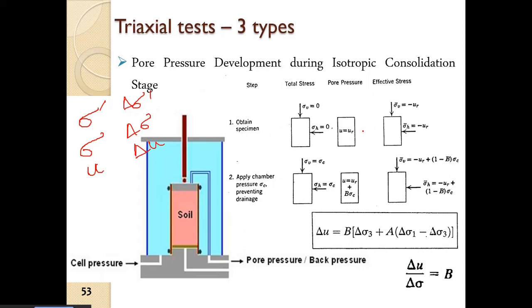If you remember, we had one sample inside the soil at a particular depth z. We had a pore water pressure of gamma w h. So this sample had an effective stress state of sigma dash equal to sigma minus u, where sigma is the unit weight of everything above, gamma bulk or gamma saturated, if there is anything on top.